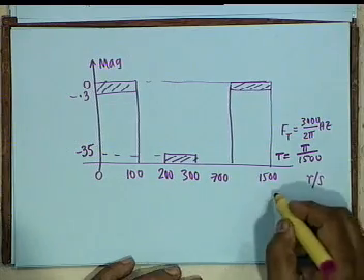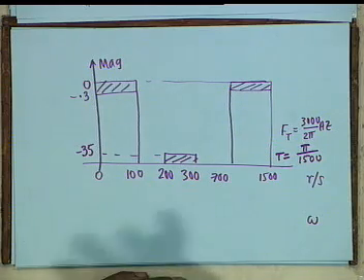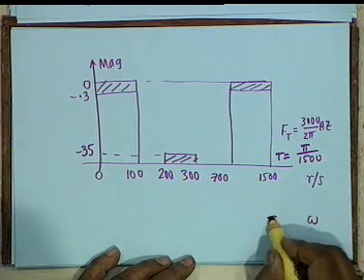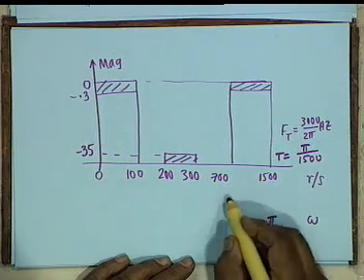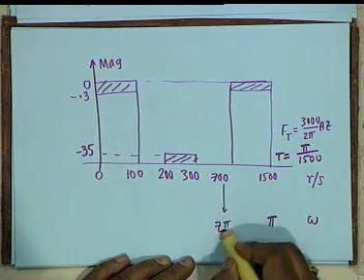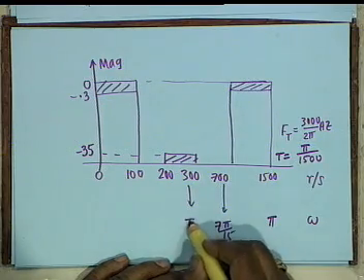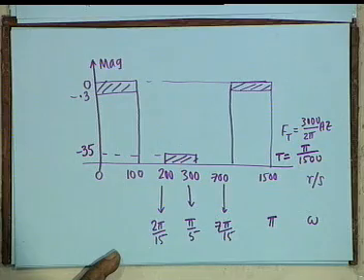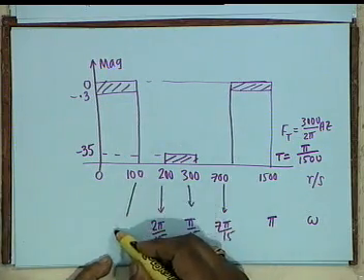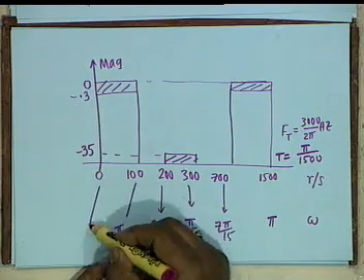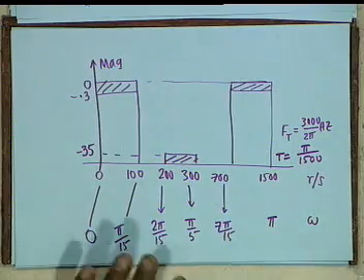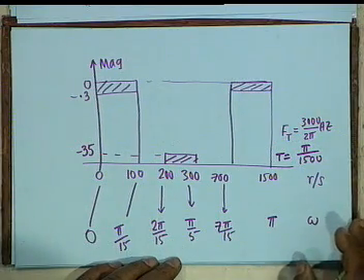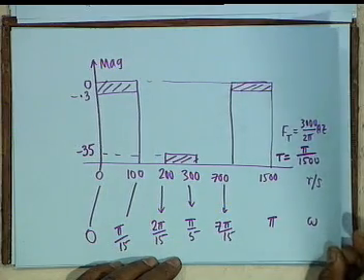So, my digital normalized, first thing to do is to convert these specs to normalized digital filter specs. Omega would be pi here, then 7 pi by 15, 3 pi by 15, which is pi by 5, this would be 2 pi by 15, 2 by 15 pi, and this would be pi by 15. This is of course 0, 0 is 0. Now we are in business. We have converted the frequency scale to normalized digital frequency.